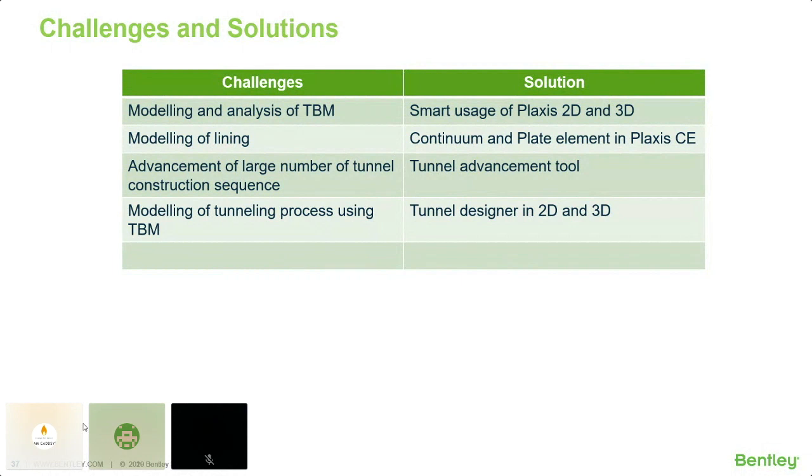Now, second is the modeling of the lining. In PLAXIS, the lining can be modeled as a continuum element or as a plate element. Now, the plate element is simple and it will give you the structural forces directly.